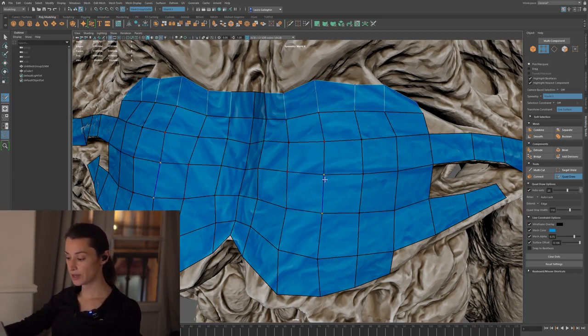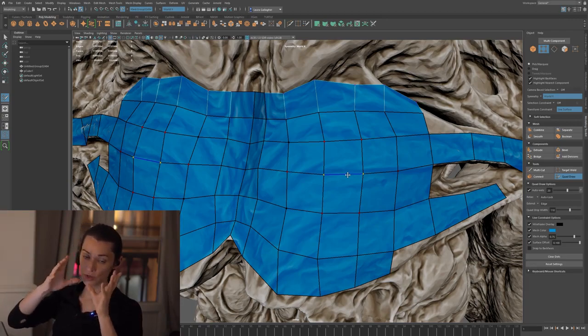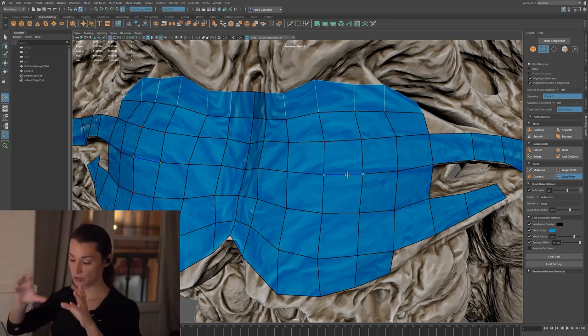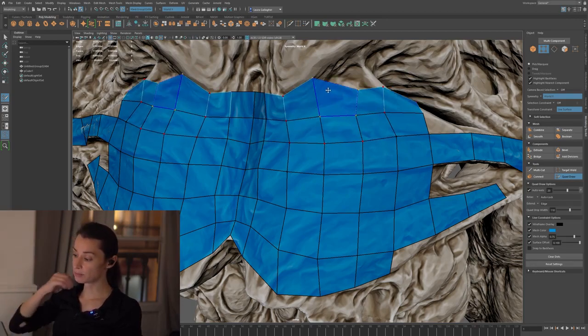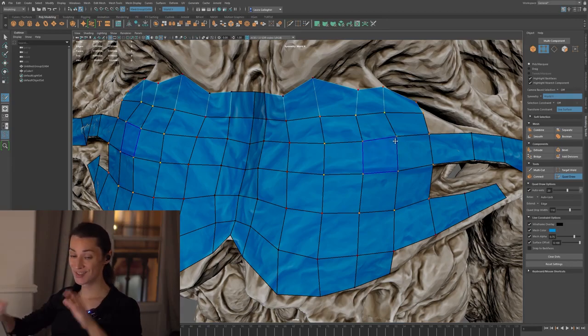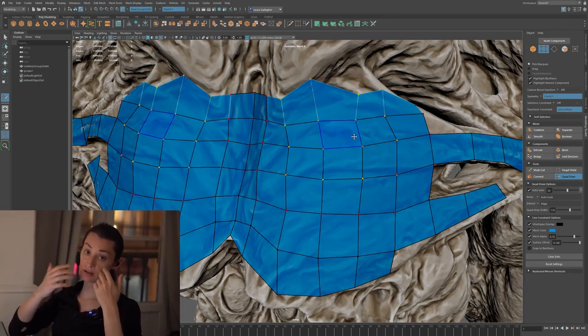Once we have pressed B here, you can see all the vertices that seem to light up around my cursor. And what's going to happen is that as I click and drag, I will move a full area of the mesh, the whole area that is highlighted when I click somewhere. That allows us to move larger areas of the mesh around at any one time. If I hold down B and click and drag, I can change the size of that highlighted zone so that when I do a move afterward, I am moving a bigger or a smaller zone.